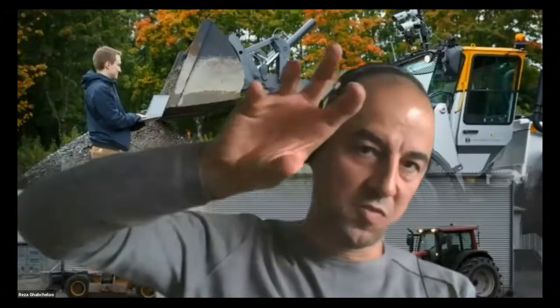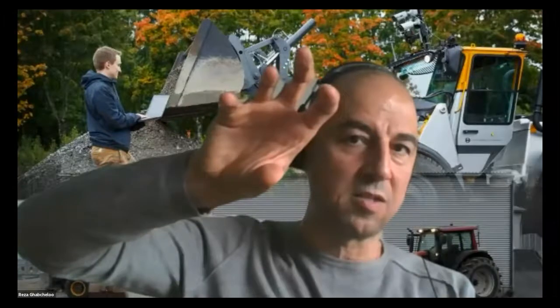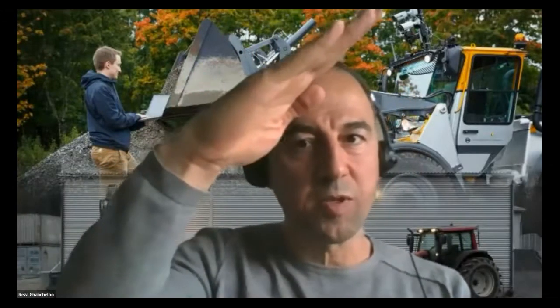Let's say, well, the manipulator. Think about a 2 degree of freedom manipulator. You have a sensor installed, okay? You don't know where the sensor is. If you connect it and measure the sensor, the encoder, if Reza installs it this way, and if Mehdi installs it, he might install it that way. So when you measure it, the same manipulator position gives you 10 degrees, the other one will give you 20 degrees. How do you define where the safety limit or the joint limit is?